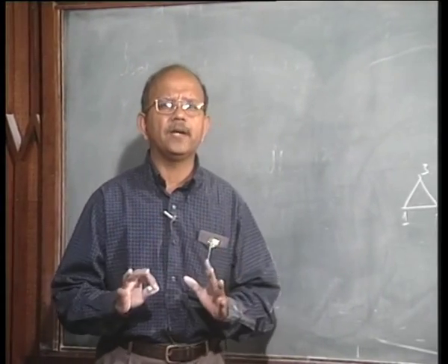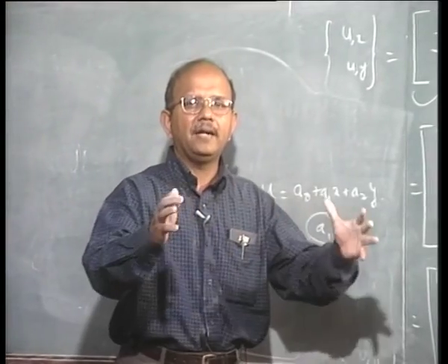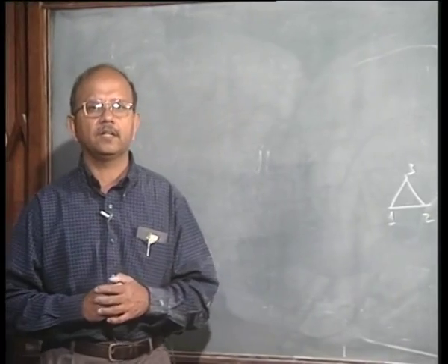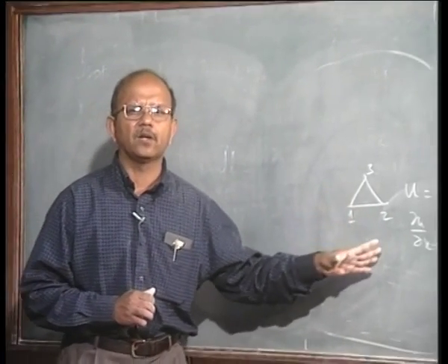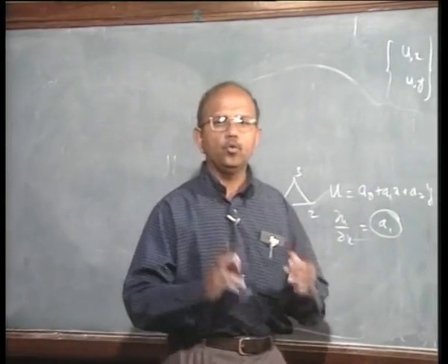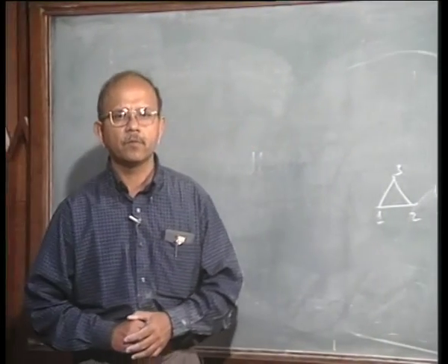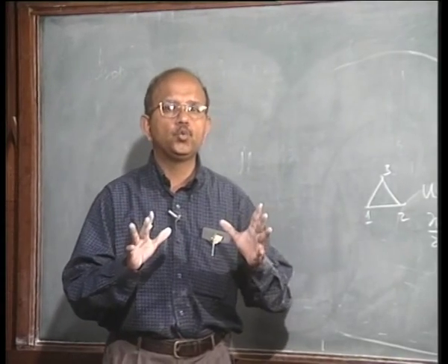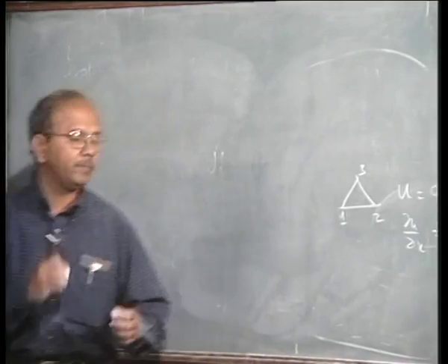With all these drawbacks, still we have to learn about the triangular element and its three-dimensional generalization, which is the tetrahedron element. We will concentrate only on the triangular element because what we are talking about in the triangular element is very similar to the tetrahedron element. So there are two procedures, two ways in which you can calculate the stiffness matrix. Procedure number 1 is to collapse two nodes in a quadrilateral element. What do we mean by that?